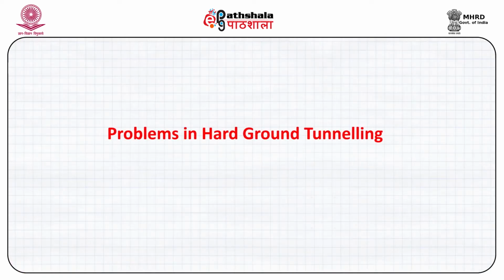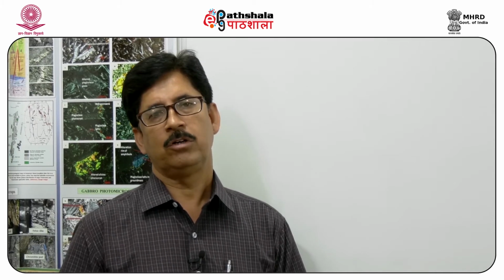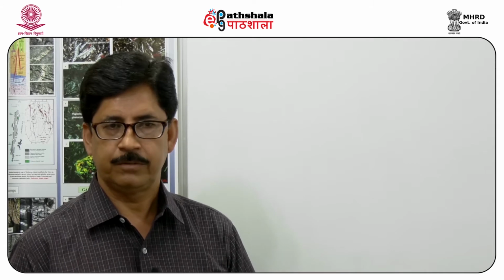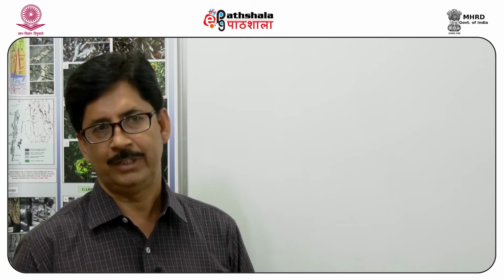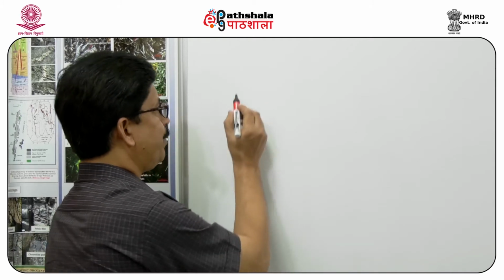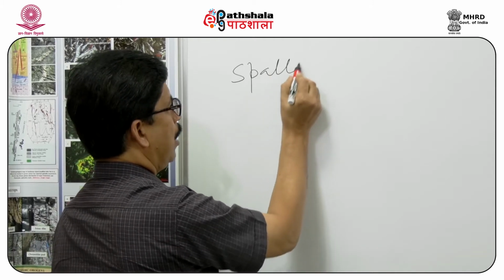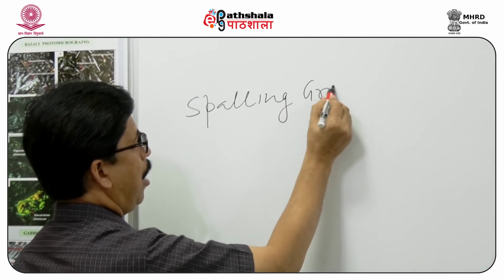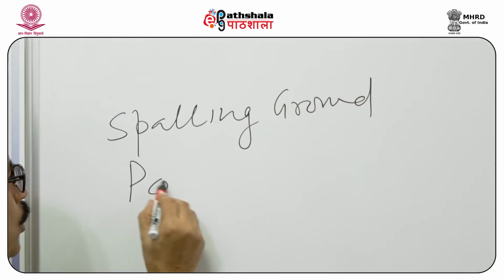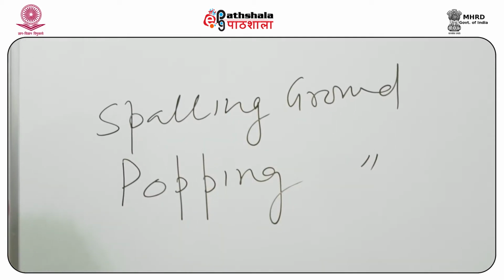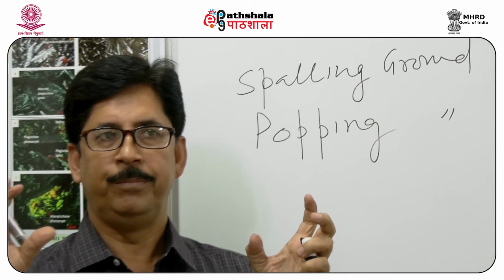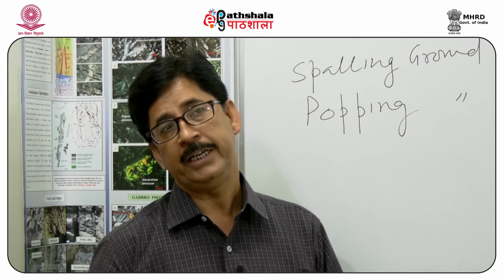Now the role of engineering geology comes when we go for hard ground tunneling, because in hard ground tunneling we have a lot of problems, for example, falling of rocks from the wall or the roof, that is called spalling ground. We may have issues of popping of rocks, that is rocks breaking and popping into the opening.